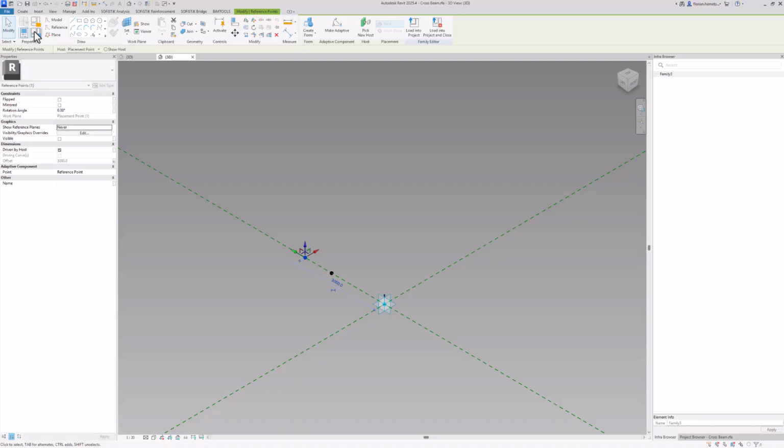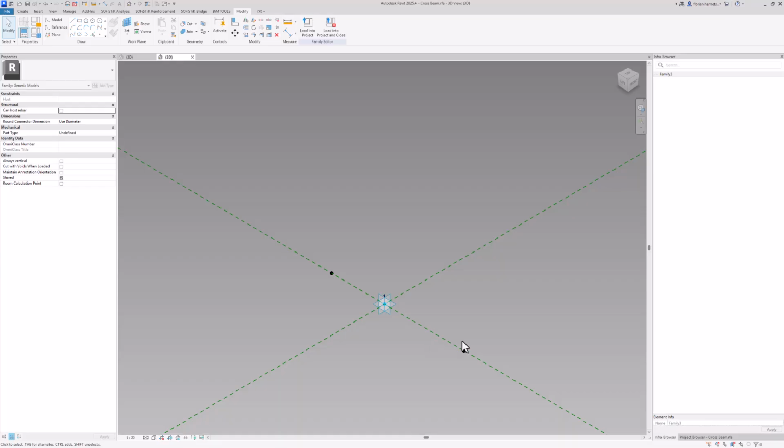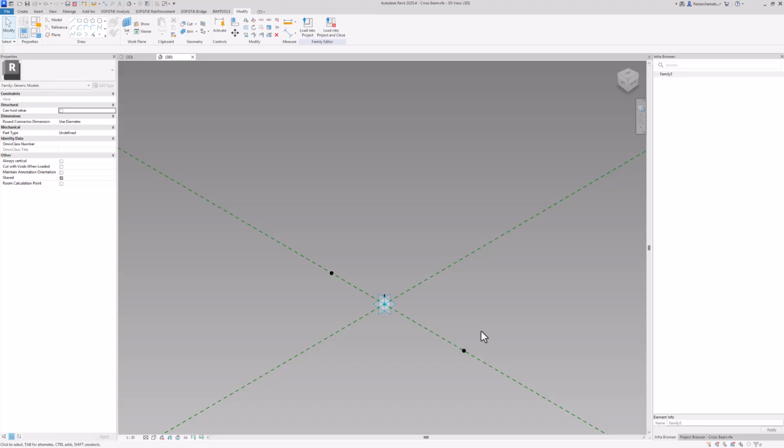So what we need to do is to either create another parameter which simply multiplies this width with -1, or we input the value with a negative. Both of them are valid approaches. Just keep in mind, you as the user have to define what the family actually does for you. Alright, so far so good.